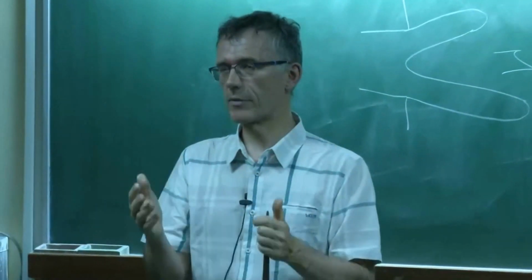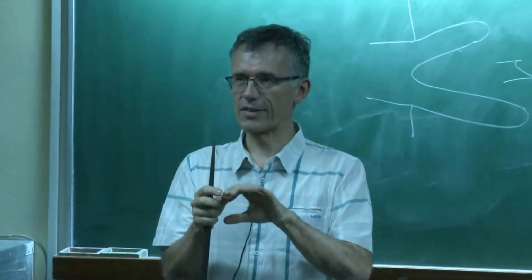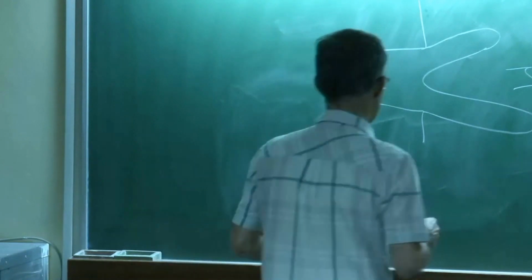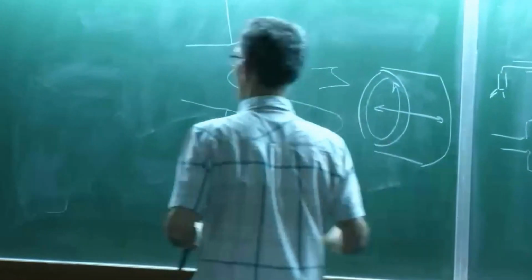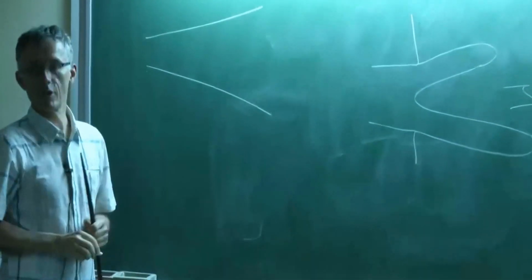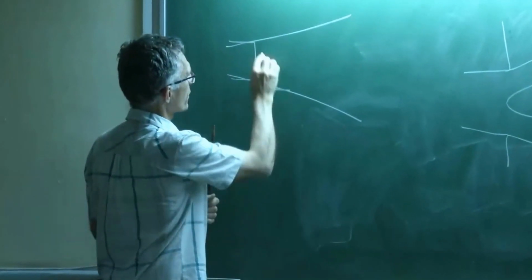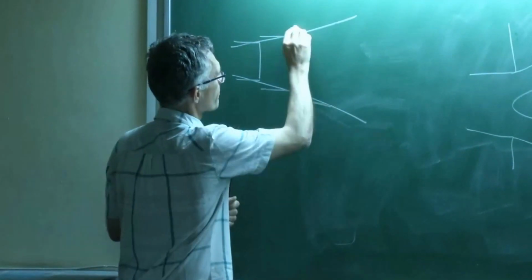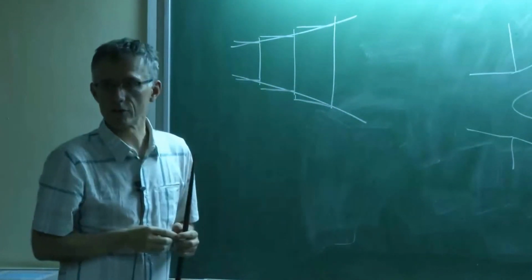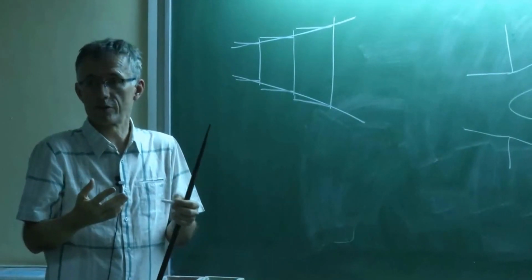Well, there is some arbitrariness when you do that, of course, because in a real system, it's not really straight elements. What you have to do is you have a criterion which tells you, for example, when you mesh a nozzle like this, basically you cut it in one first piece here, then you have a second one here, etc. And this is approximate, of course, but it's basically a one-dimensional discretization of space.